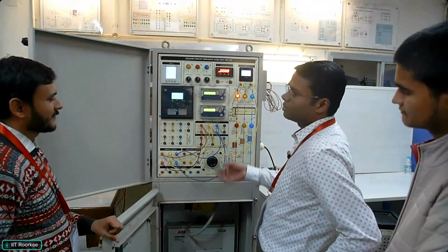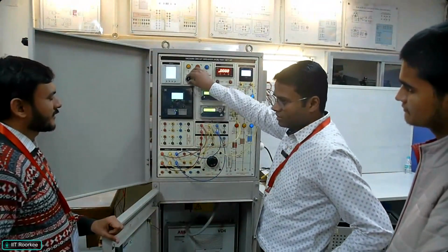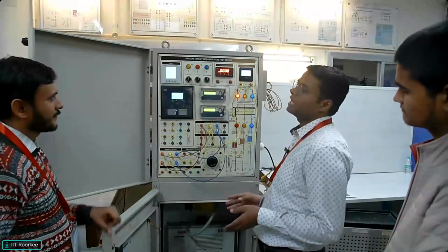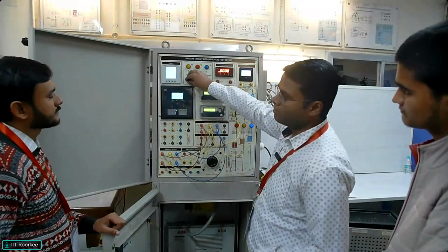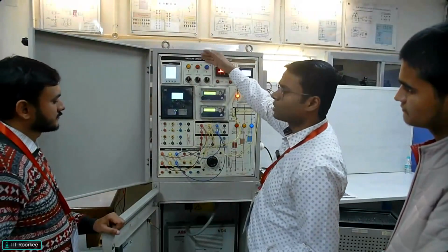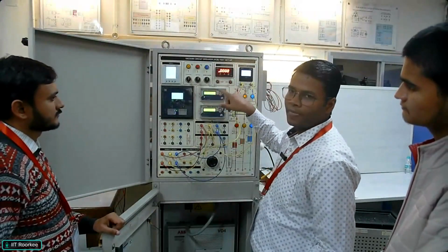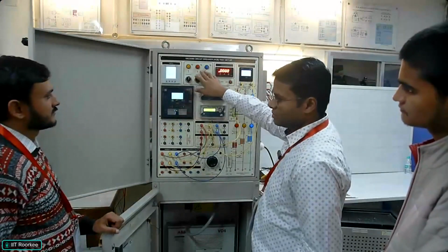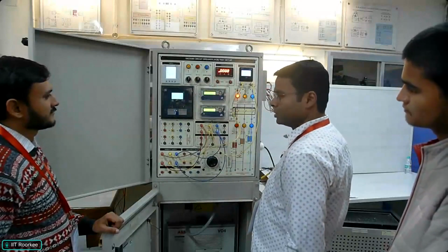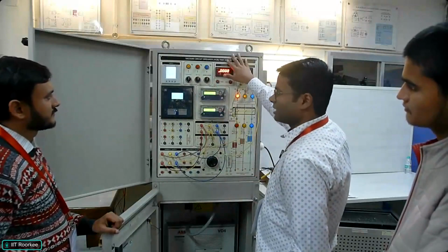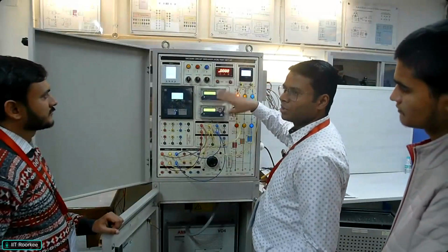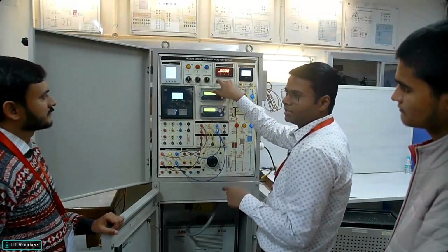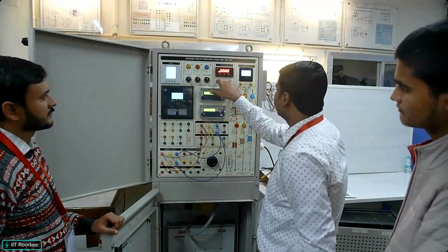The closing spring will be charged with this close button. When you operate the close coil button, a servo motor connected to it charges the spring. The trip coil, close coil, and spring charging mechanism I will also explain when I do the experiment. Here we are putting the timer. This timer is not automatic. We need to put it manually. So when I start the operation, I will simultaneously push that.